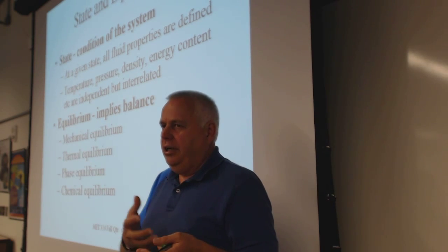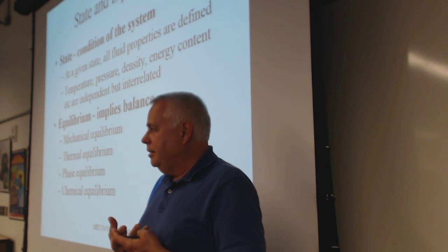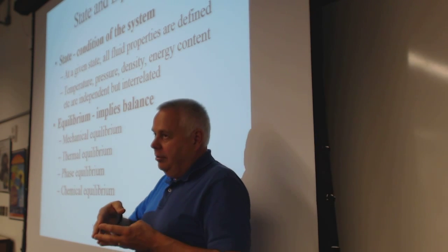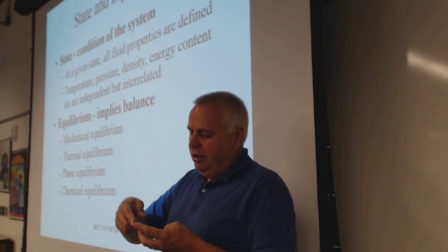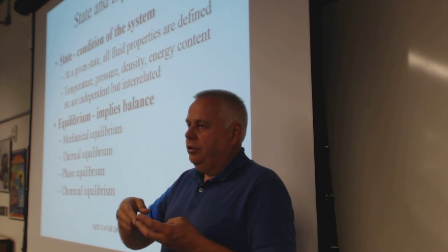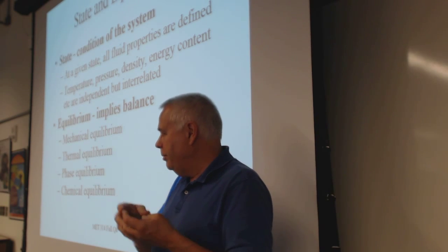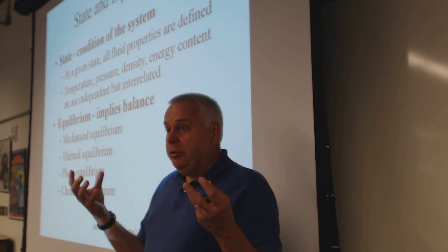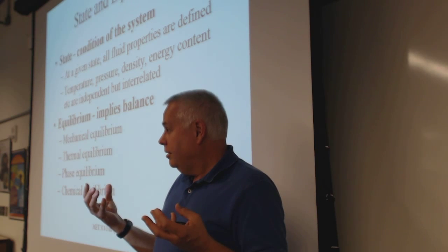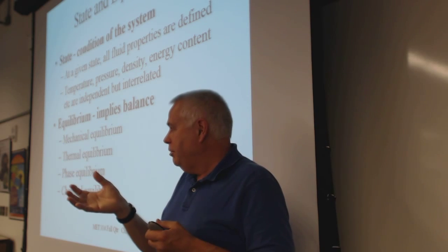It's going to stop being air and fuel. Combustion, we'll find out eventually, is taking a hydrocarbon and burning it, and it becomes water, essentially steam, and CO2, and whatever oxygen and nitrogen didn't get burned will also be part of that soup. So now it's changed temperatures, and it's changed pressures, just because, well, we probably compressed it first, I hope, otherwise it would be pre-ignition.